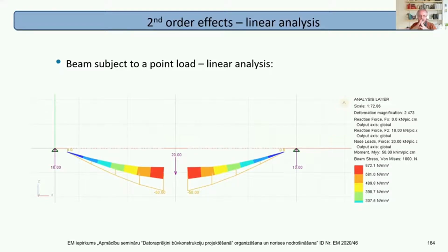Now, we know that if this was a steel beam, it would have yielded. This is a linear analysis, but it's giving us results saying this beam cannot carry that load. I know we might use it to calculate a different beam, but as is, the stress is saying that something is very wrong. If we're analyzing this beam section, this linear analysis is giving us wrong results, essentially. The calculations are correct, but the assumptions are not.